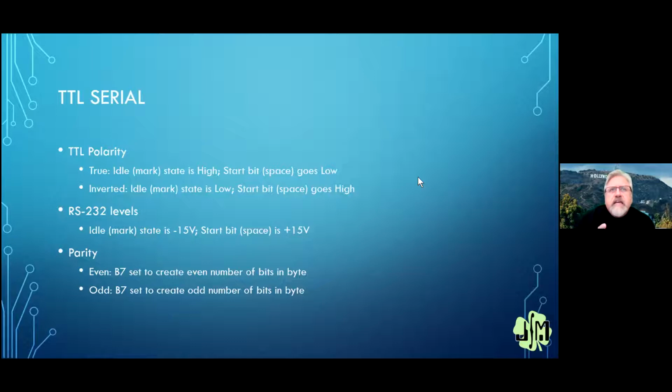So you'll see, for example, 8N1. That's a very typical descriptor of a serial byte, which is 8 data bits, no parity, so we're using all 8 of the data bits, and we have 1 stop bit. You might, for example, though, see 7E2. It's an odd thing, but that's 7 data bits, we're using even parity, so that's where that other bit is going, and then we're going to have 2 stop bits. Okay, makes sense. It's pretty straightforward.